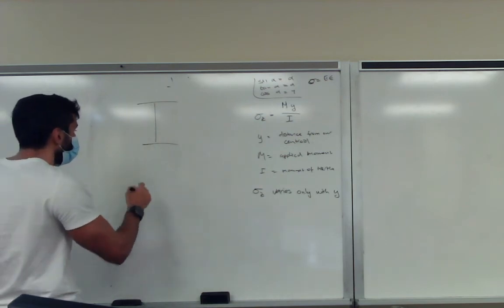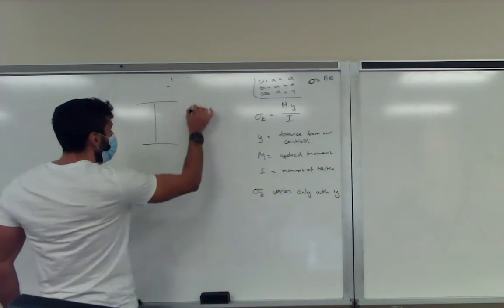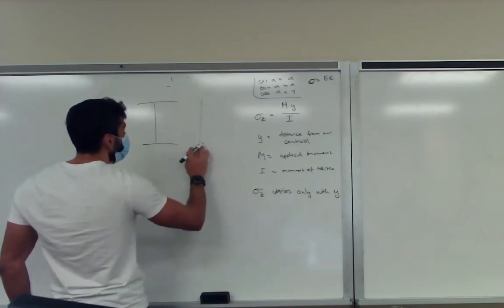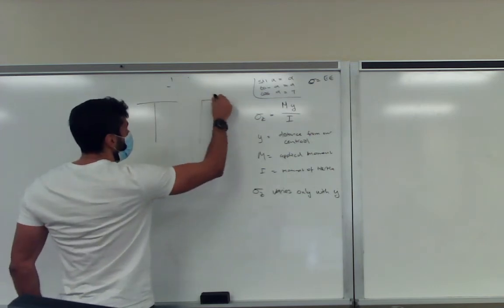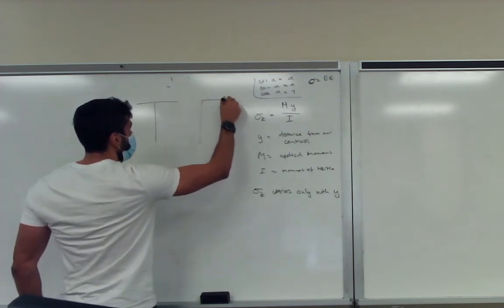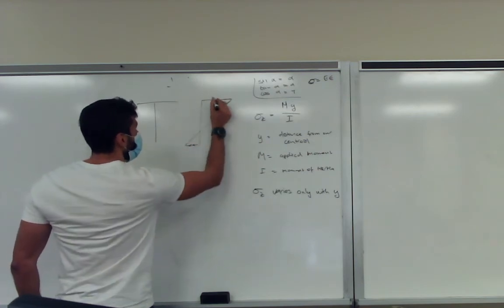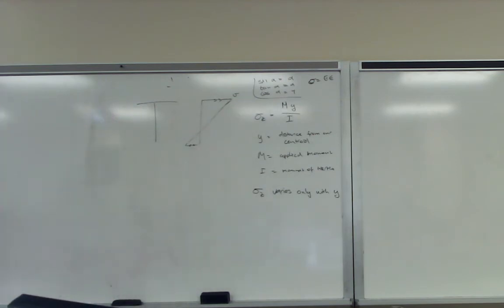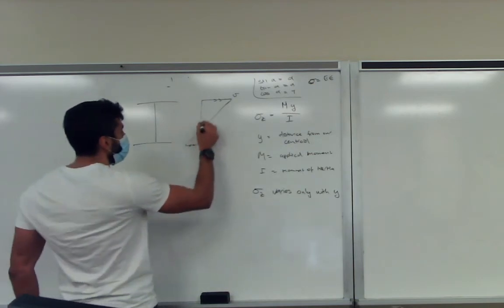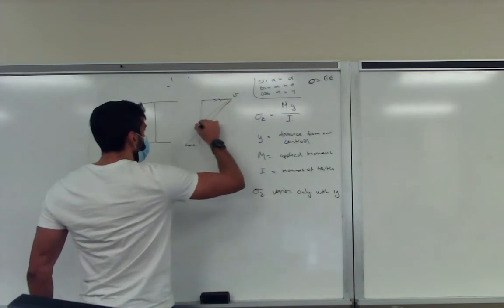If we look at the direct stresses, it will be something like this. In this case, it's doubly symmetric. Then we get large stresses at the top and small stresses at the bottom. This will be the shape of our stress distribution in the thickness direction. If it is symmetric, then we know that the neutral axis goes through our center.